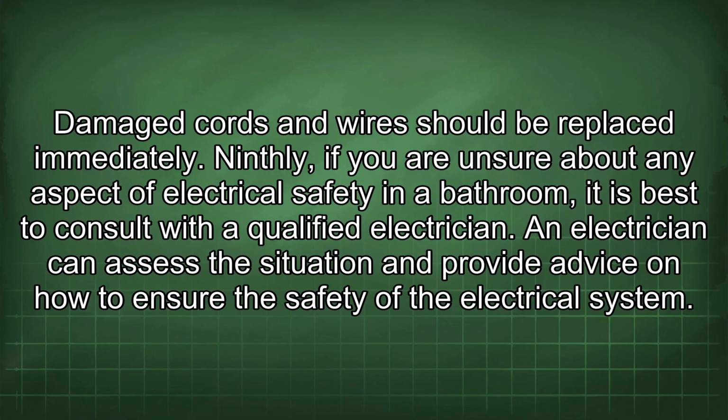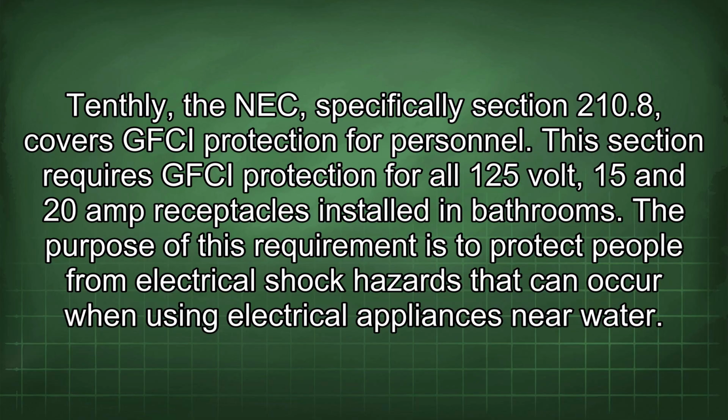Tenthly, the NEC, specifically Section 210.8, covers GFCI protection for personnel. This section requires GFCI protection for all 125-volt, 15 and 20 amp receptacles installed in bathrooms. The purpose of this requirement is to protect people from electrical shock hazards that can occur when using electrical appliances near water.